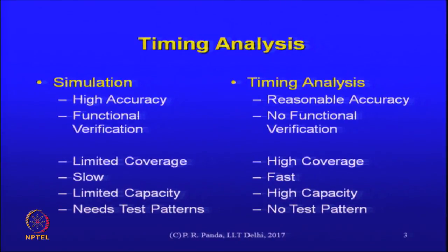Simulation actually does a lot more than just the timing. It does functional verification, right? You look at the logic output and decide whether it's working or not. Whether the functionality is working or not. Timing analysis has no such feature. It only tells you timing. Everything may be wrong, but your critical path might look good. It actually might be a very fast circuit that does something that is not required.